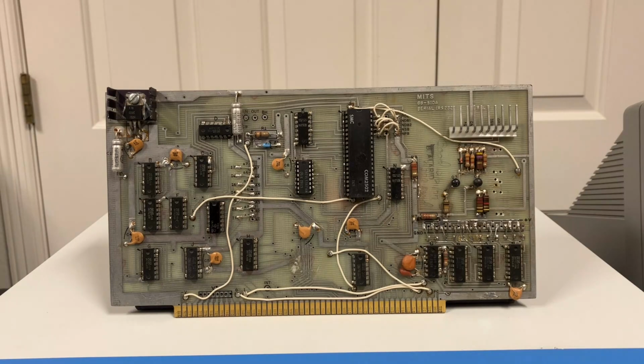The next thing we need to do is make sure that the receive data available flag is on bit 0, and the transmit ready flag is on bit 7 of the status word, and those bits use negative logic, meaning 0 is true. Now this is the SIO board, the same as used in the cassette interface, so you would think I don't have to worry about that. However, you do, and the reason is because the very first versions of this board did not work that way.